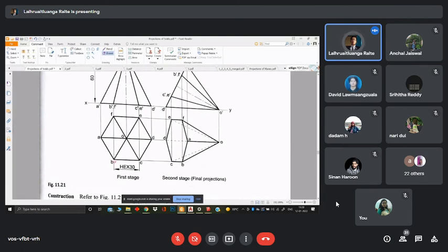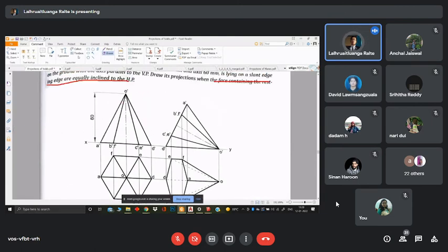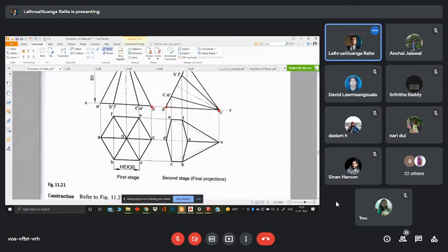So we are forming our hexagon and our front view like this. Now the front view is fixed and we let it sleep. We entirely rotate it, making OD sleep on the XY line. This whole thing is rotated and let to sleep like this, and from then we get the points to get the true top view.